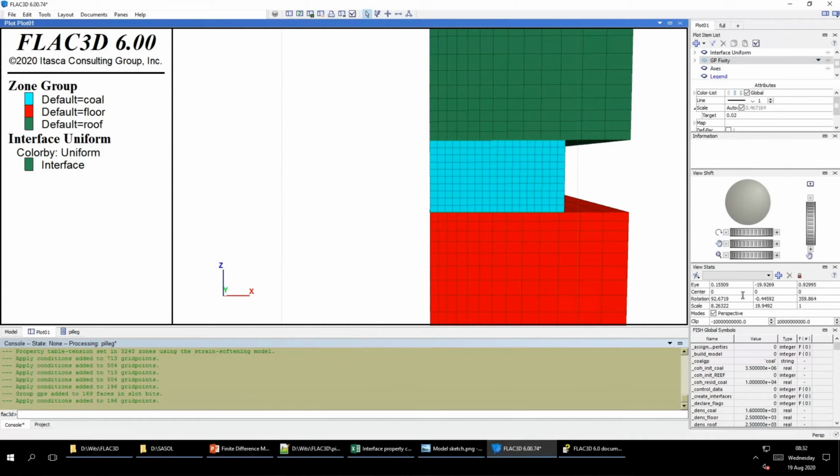Okay, and you'll see here my rotation. If I want to view this thing edge on, my rotations obviously need to be multiples of 90. So I'm just going to go, the closest is 90, 0, and 360 is 0. So now I'm looking directly edge on exactly where I want to be. And you see the only variable that really has a value now is that 90 degrees to give you the angle, and this minus 19, which is the distance away from where I'm looking at the model.